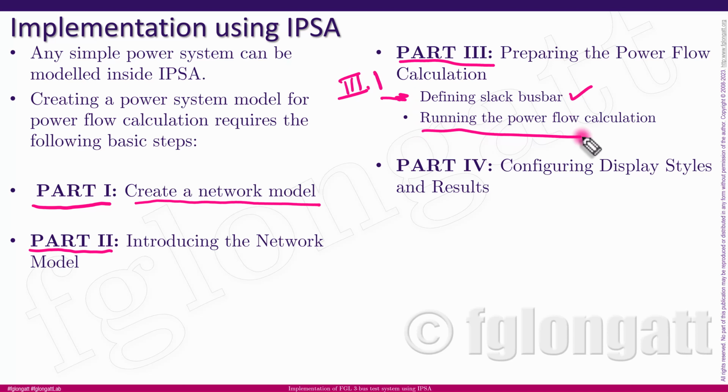And when we finish running the load flow, one of the interesting features about IPSA is that you can get the numerical results of the load flow or power flow inside the graphical representation. So the final step is configuring the display of styles and results inside the software. That is basically 4 parts. And if you follow these parts in this very systematic way, you will be able to reuse this video and you can create any other test system.